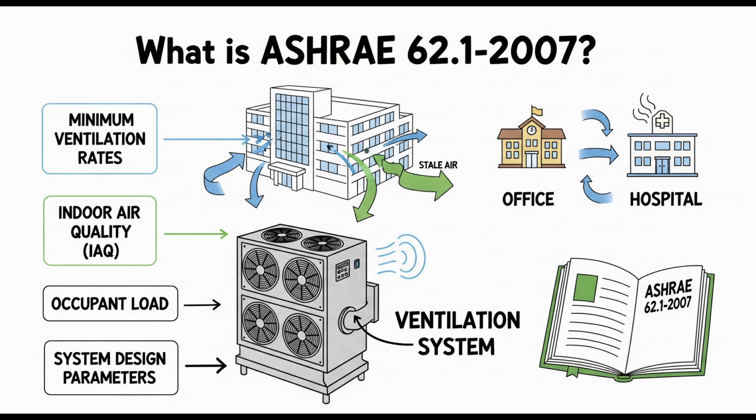That visual really helps. So you can't just stick the fresh air intake right above the dumpster or next to the lab exhaust. Seems obvious, but clearly needs to be a hard rule. Absolutely needs to be. Then there's filtration, another key piece, Section 5.9.